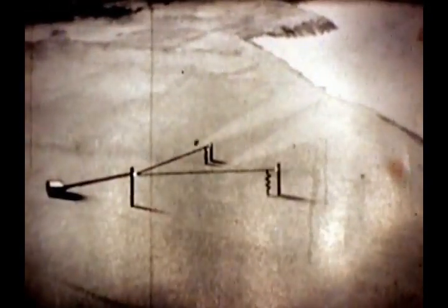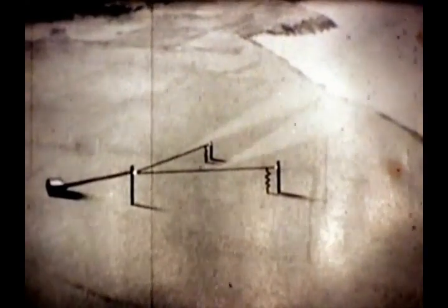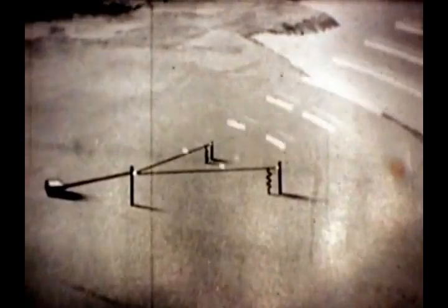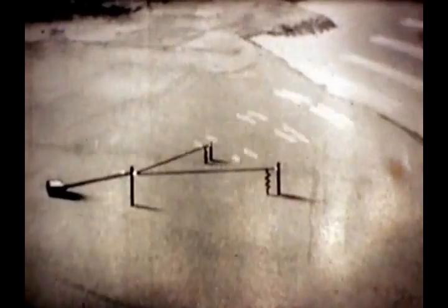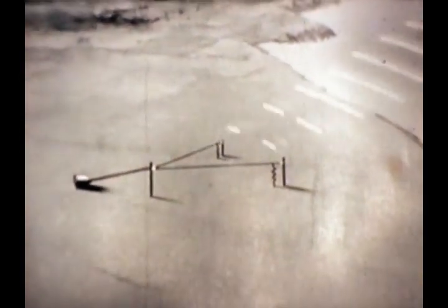A further development in the construction of this type of antenna is the addition of a second long wire at an angle with the first. The combination of the radiated energy from both wires of the V antenna produces a wave pattern with greater directivity. Now then, to reach the desired transoceanic point, this wave pattern is projected toward the sky, where it hits the ionosphere. So, the main job of the long wire or V antenna is to beam as much energy as possible into the sky at an angle so that the beam can be returned to the Earth at the desired point